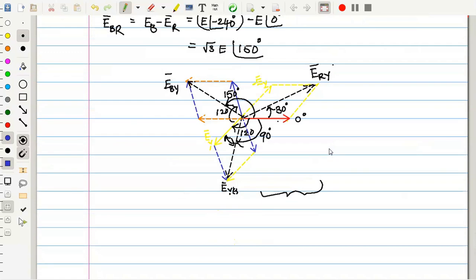I hope everybody worked out on this phasor diagram. From the phase voltages of R, Y and B, first you take the negative voltages of all these, which is at 180 degrees, in phase opposition. Like R is here, ER, Y is here, EY, and B is here, minus EB. Then you add up ER and minus EY, you will get ERY. Try to observe that this line voltage is leading the phase voltage by 30 degrees.